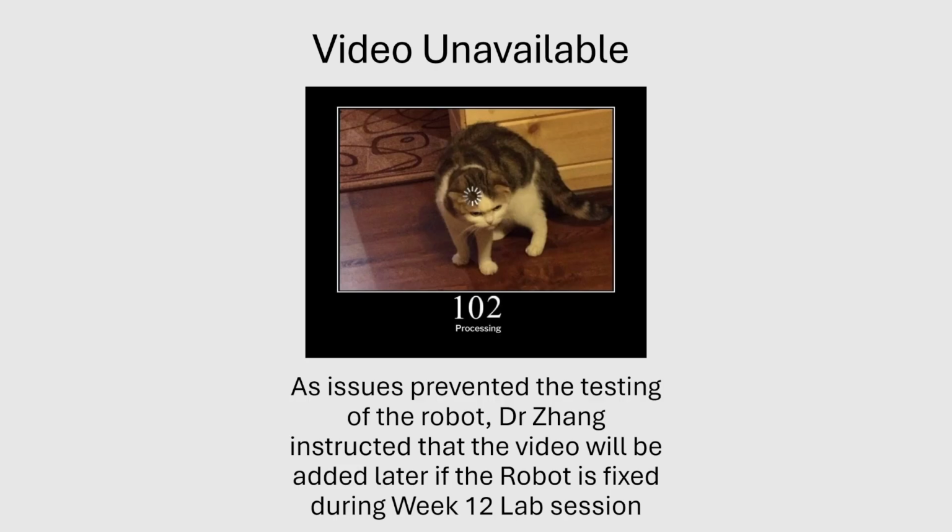Using a separate terminal, we launch the teleoperation node, which allows us to send commands directly from our keyboard to the robot's motion controller. These commands are sent as velocity messages, and we can immediately see their effect on the robot's movement inside the virtual world. Even though there is no video of our own for this task for now, the expected behavior is that the robot should translate and rotate smoothly as we navigate around the environment. This demonstrates the essential communication pathway between user input, ROS messages, and robot action, a key interface that carries through every other task we perform.